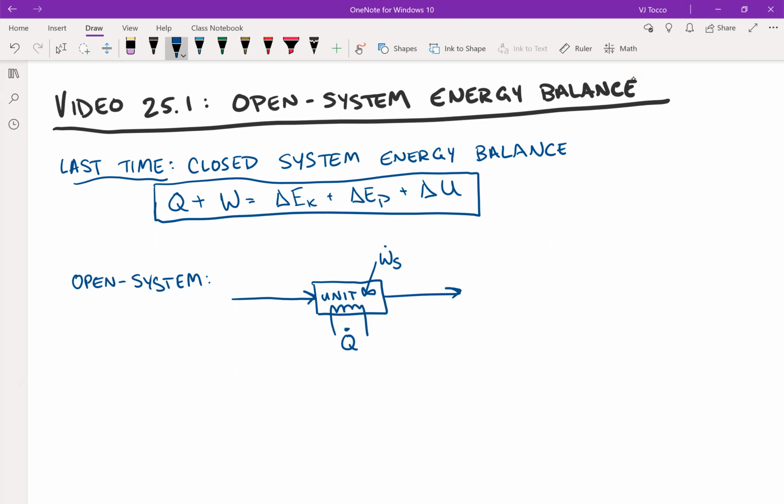So just as before, let's start by just considering the general balance equation. In plus generation minus out minus consumption. It's always a good place to start when considering any type of balance. We will start by assuming that the open system energy balance is at steady state, and energy can be neither generated nor consumed. And I made a mistake here. So even though we're at steady state, we're not going to cancel the accumulation term